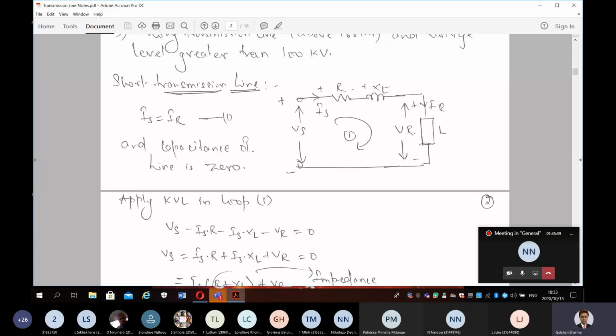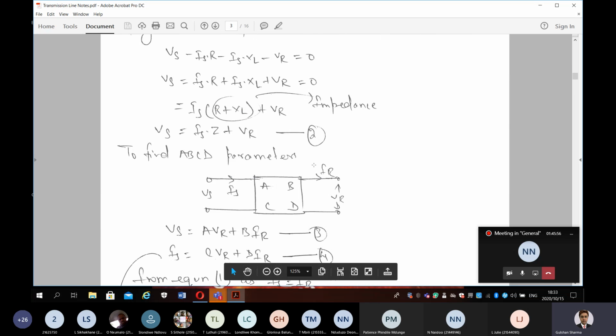According to that, your phasor will change. You know that for resistive, your voltage and current should be in phase. For inductive, current should lag the voltage by an angle, but it's not 90 degrees, it's less than 90. For capacitive, your current should lead the voltage. Okay, so that's one concern.